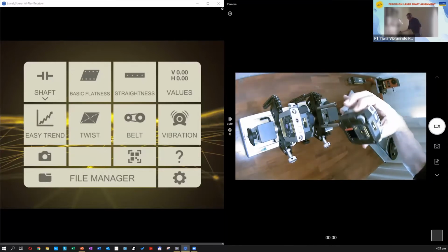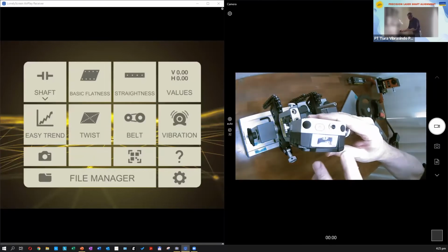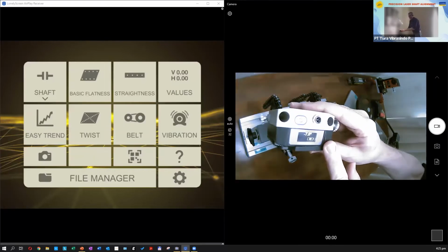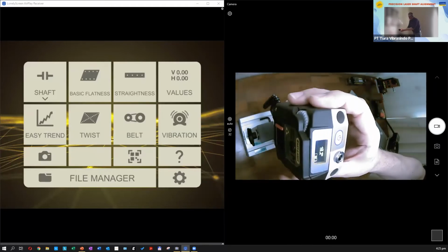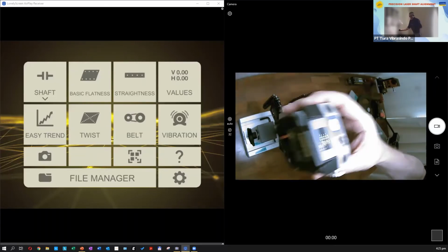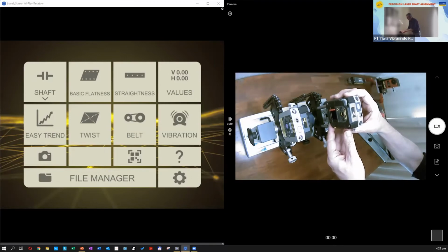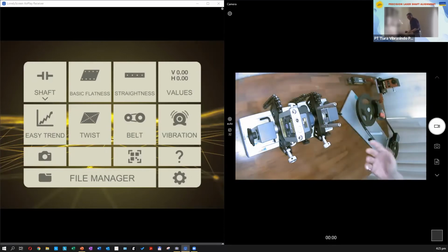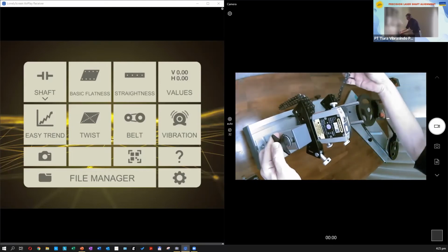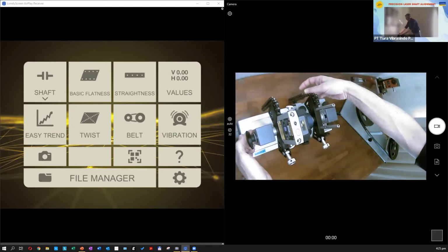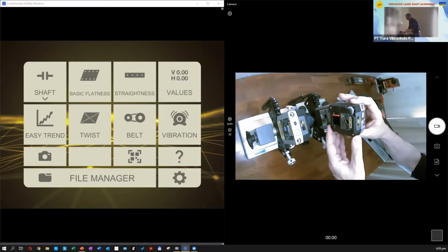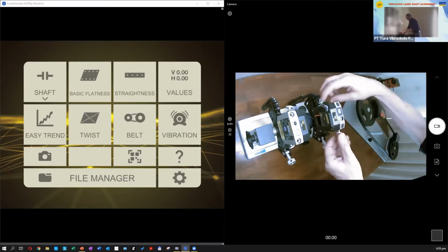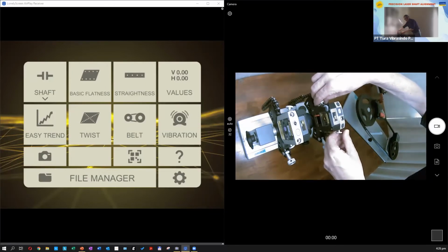One very nice feature that I particularly like is that we see the inclination on the measurement instrument directly on it. So I always know at which angle the measurement unit is placed. It can be very helpful when adjusting and putting it on the brackets. The brackets, as we have seen in the video, are classical V brackets put on the shaft and tightened, and we have our two posts where the measurement unit sits and is secured through the holding screws.